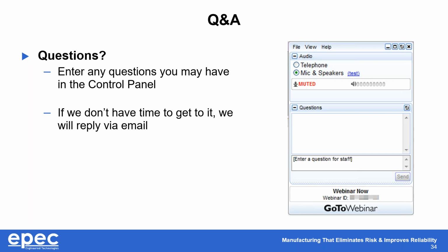So that's where many times if a customer is looking for something quickly and sends us a design that has the coverlay going all the way through, that can cause us to slow down a little bit as we go through and do a redesign, because now your stack up and your overall thicknesses can change and need to be addressed. So that's one of the biggest things we see.